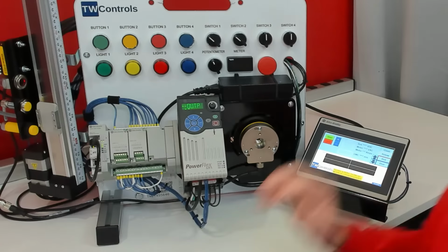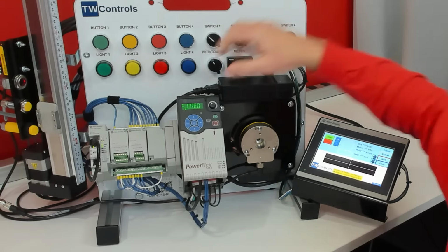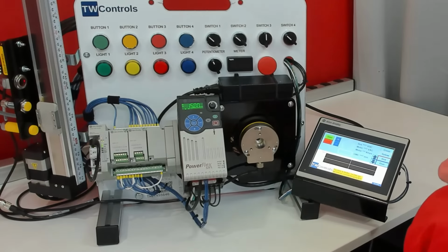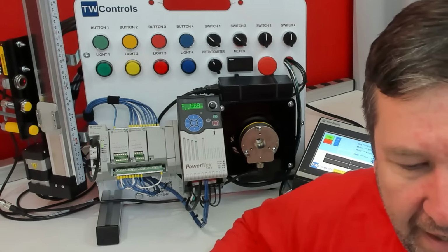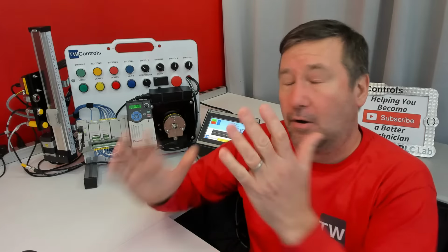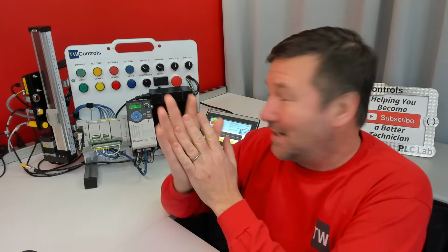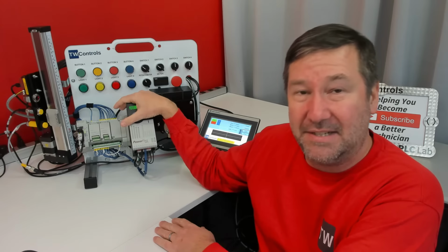And now, if we switch over to the left, whoops, get that back where it was, then we're running 15 hertz. So that gets us through our input scaling. I mean, our output scaling, actually. That gets us through our drive speed scaling.